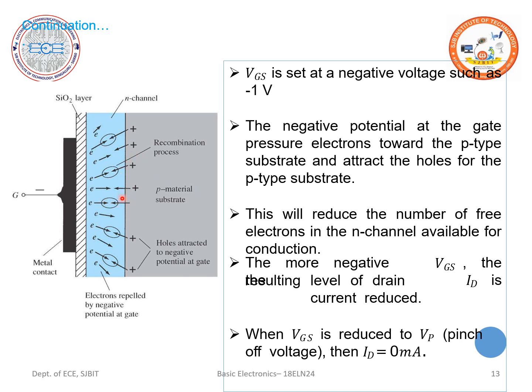The positive potential at the gate induces negative charges in the p substrate. This charge results from minority carriers attracted towards the area of the gate.